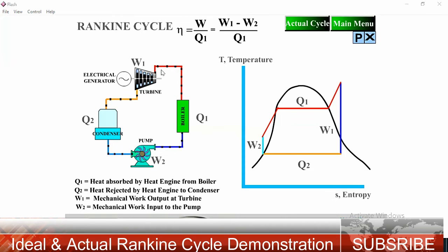In process 1 to 2, mechanical work is obtained by expanding superheated steam in the turbine, and the process is made adiabatic. Process speed is increased and the system is made insulated. Normally, asbestos material is used on the turbine cover for insulation, so the process is adiabatic, and the bearing friction and viscous friction are negligible.